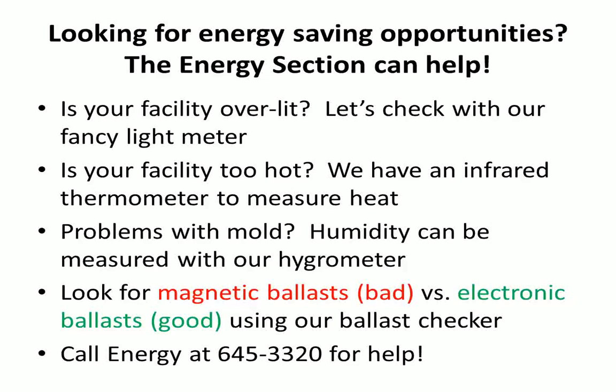Is your facility too hot? This is a common complaint. Well, you've got to prove it. We have an infrared thermometer here that you can use to measure the temperature of your facility or rooms within your facility. The problems with mold. We have a hygrometer here that can measure the humidity, and based on the temperature and humidity, we can figure out if you have conditions for mold in your facility. So these are all your responsibility, and we'll provide you with the tools and the know-how to follow up on all these issues.